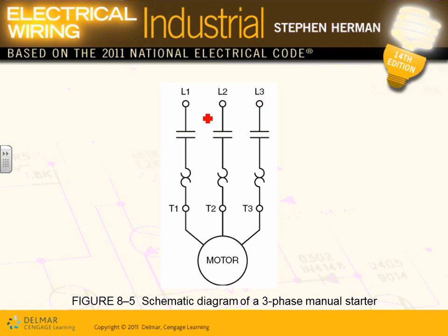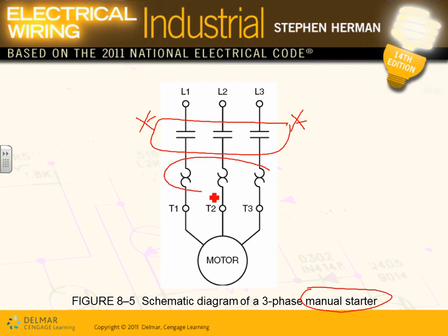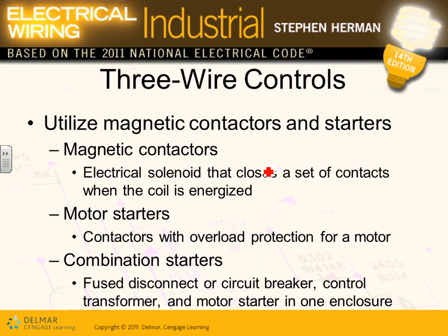Manual starters, this is review probably for you too, Matt. When you go to our second quarter with Jeff, he'll say, grab a manual three-phase starter, and you're going to go grab that manual three-phase starter and bring it. These contacts, guys, are not driven by a coil. They are driven by a physical mechanical movement. And these are the overload heaters, typically with it, or coils, your heaters, to protect you from overload. Three-phase: phase A, phase B, phase C.